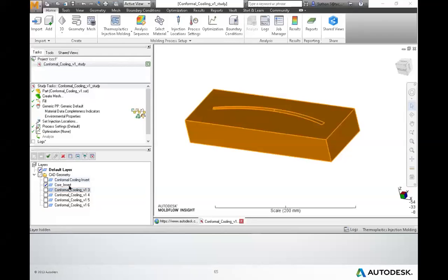If you use the method of that button from Fusion 360 inside Moldflow, we have to rename the parts, because it uses the assembly name to assign to the part. But if we use the exporting technique, the name attaches to the part itself, and once we import, we don't have to rename.